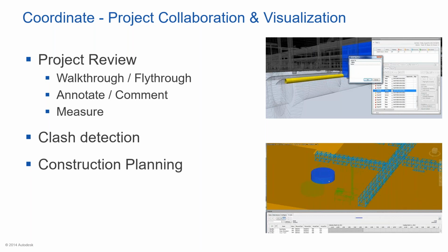Preferably, we could utilize tools like Navisworks or Navisworks Manage in this case to create a quick clash check, create a quick report, create a quick walkthrough or a fly-through of my plant project, annotate that piece of information, comment on that, create markups on that, or measure that particular piece of information for project reviewing purposes. I could go one step ahead. I could create a clash detection report. It could be in the form of a PDF or HTML report in this case, which could be assigned or shared to the respective disciplines who form a part of my project, basically.